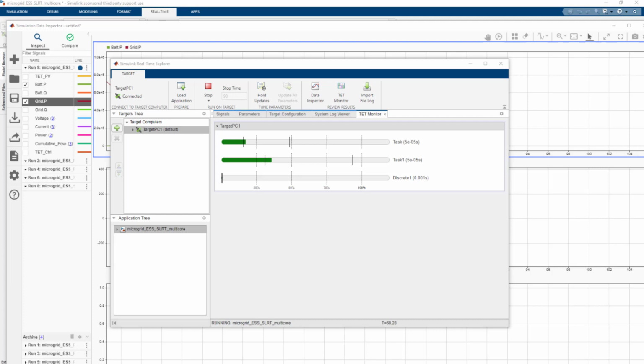This is just an example of scaling up your HIL simulation capability. As we mentioned before, besides the multi-core simulation, Simscape can also support multi-target HIL simulation by running the model in several target machines by using shared memory with very small latencies.